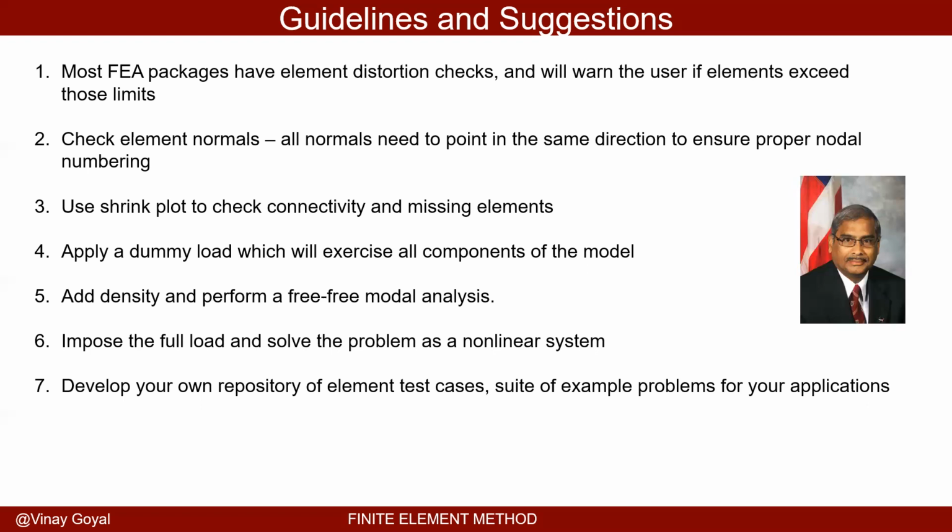Develop your own repository of element test cases, a suite of example problems for your applications. This is what I would suggest you should do once you settle down in a job someplace. You have to develop your own test cases of elements, and you have to have favorite elements which will always give you a good answer, or you have to develop a confidence in those elements. Look at the MacNeal-Harder paper, which will tell you all kinds of things which can go wrong. It's a very beautiful paper. Okay, can I have the next one, please?